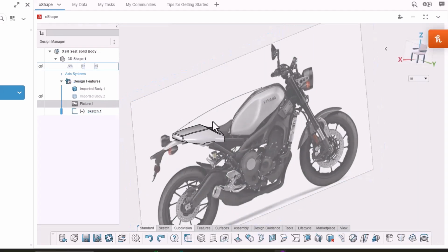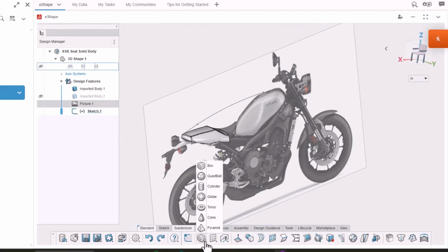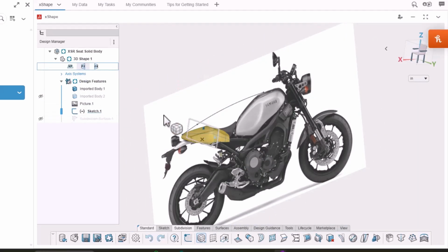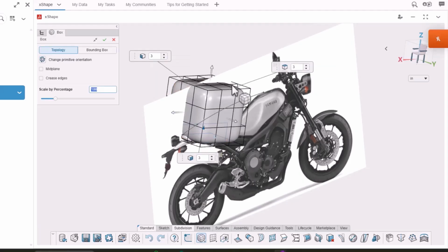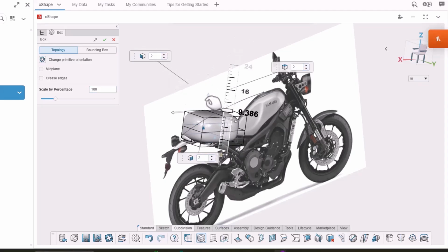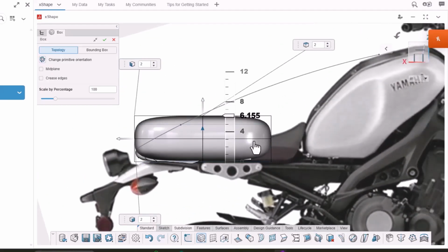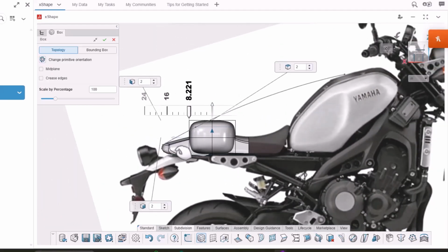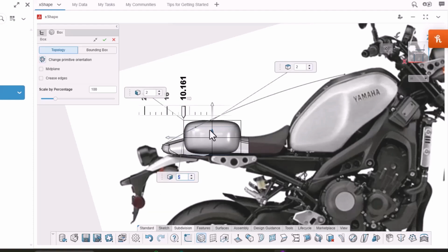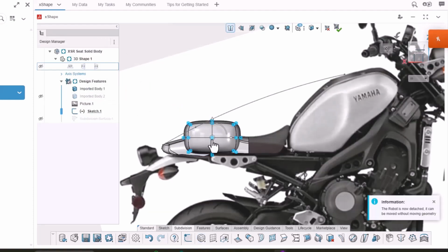Then it was finally time to move on to the sculpting part. You start with what's called a subdivision, and it's essentially a piece of clay with adjustment points attached to it. You can push and pull on those points, edges, or faces to mold out basically the shape that you want. And you really want to start with as few adjustment points as possible in the beginning, rough out your shape, and then you can add more points and edges as you go if you need them.